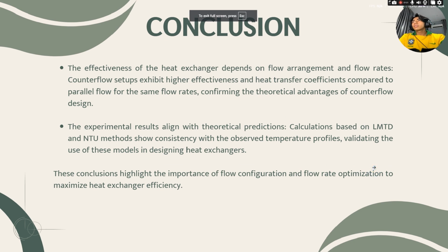Next, the effectiveness of the heat exchangers depends on flow arrangement and flow rates. Counterflow setups exhibit higher effectiveness and heat transfer coefficients compared to parallel flow for the same flow rates, confirming the theoretical advantages of counterflow design.